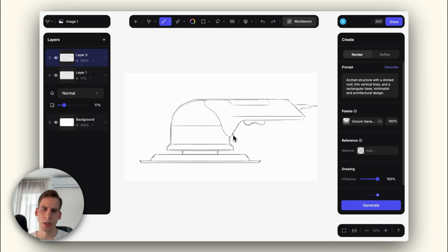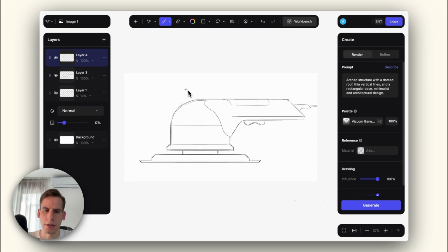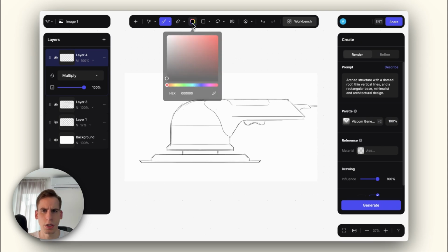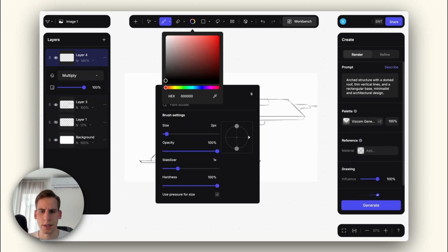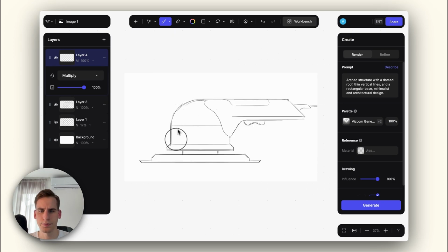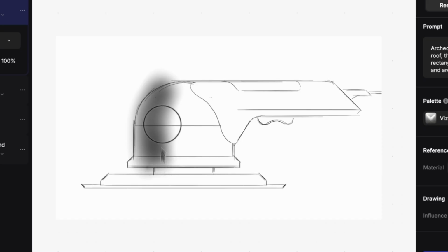So what I'll do is, the line sketch can be a good input, but that can still be misinterpreted. Vizcom can read the contrast as well. So if you want to give it a bit more sense of shape and sense of contrast, I'm going to start blocking out some of the elements and apply a basic shading before that. Now I can do that by setting the brush tool to pretty soft to just basically give it a lighter shading.